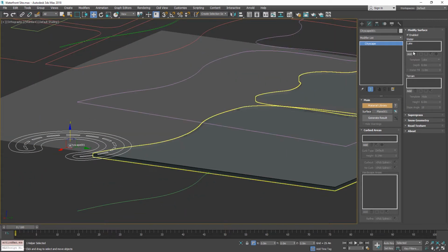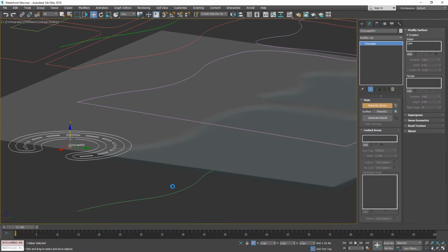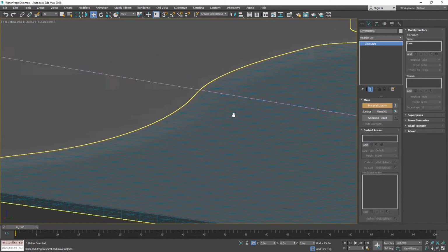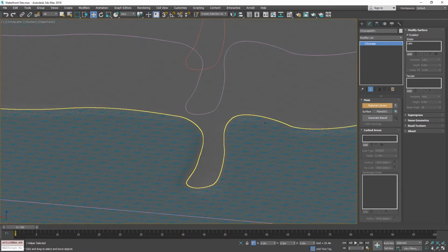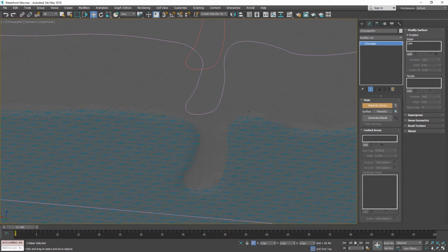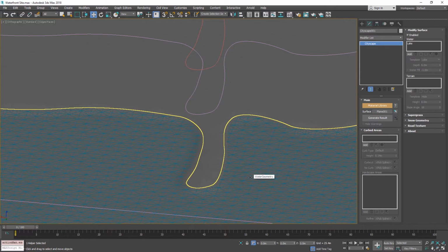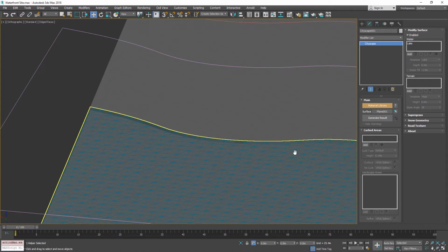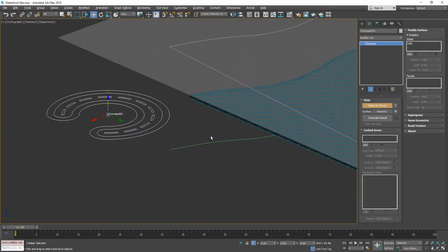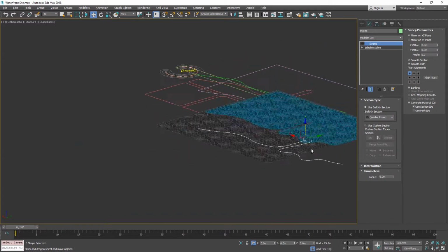However, we can change it to lake if we like to, which will give you that gradual slope everywhere. But typically on complex waterfront areas like that, you might have different types of banks. Sometimes it's just a gradual slope, sometimes it's a concrete wall. So for more control, it's usually more suitable to start with a reservoir template. And if you need a certain area, like if you want to create a beach in a certain area, you can insert a custom model, like a custom sweep, which can be just a simple line.